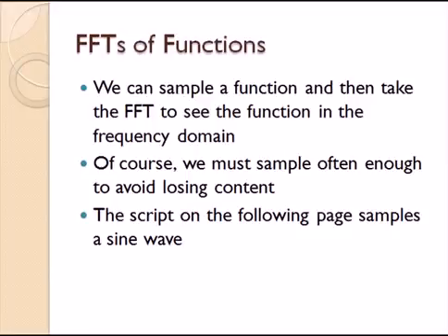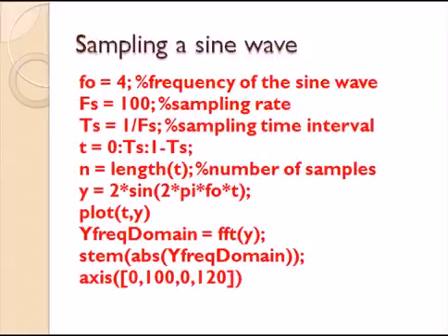So it's pretty straightforward to take an FFT of any data set in Matlab. I'm going to assume in this that the data has been collected at a constant sampling rate, right? So there's an equal time between data points, and it's trivial to do. The only tricky thing is connecting what you get to a frequency, and I'll show you how to do that as we go. So here's just an example. Most of this script is just generating a set of data. So the first 7 lines of this are just generating the data set using a sine wave, and then the real interesting part is just this FFT command down here.